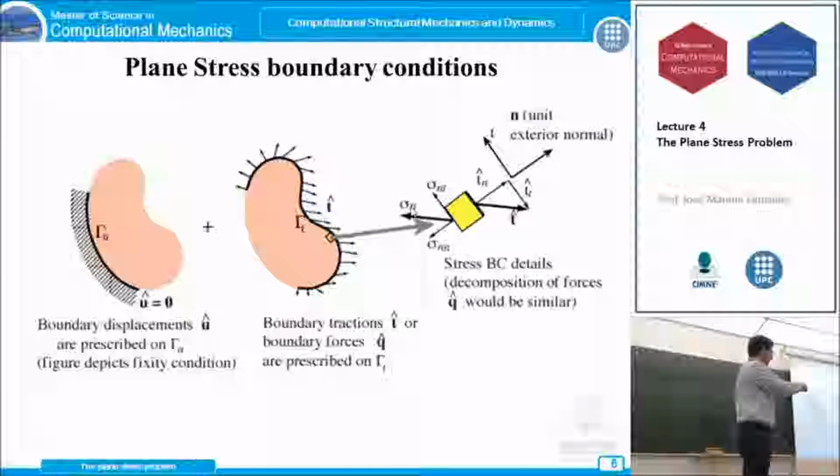So we can have as well stress boundary conditions, which is the tension applied in the boundary condition in this element here. We have a normal and tangential component from the stress along the thickness, where we consider this stress as a constant value.